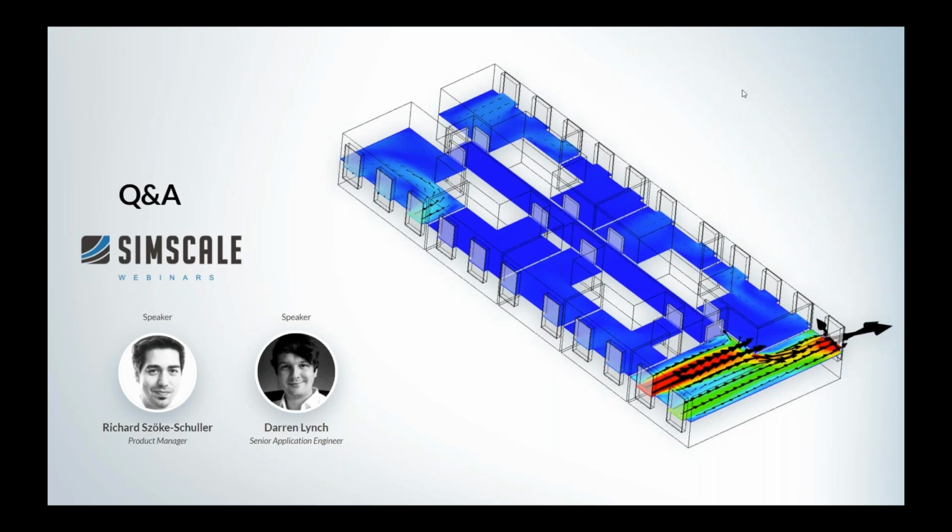So I've got another question. How were the opening angles of the windows modelled? I think I'll answer that one. When we wrote this script to take the pressure coefficients from the external flow analysis to the indoor flow analysis, we also used a calculation provided by a UK government site. I think the original source was in spreadsheet form, which we implemented into code.